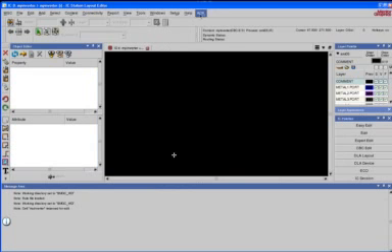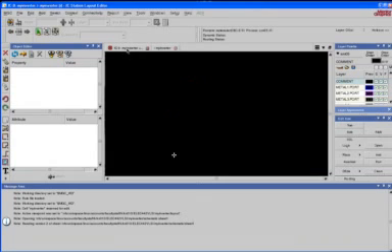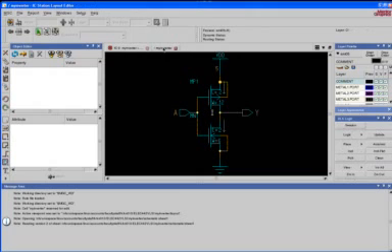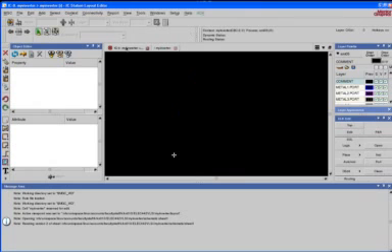Now this would bring up a window for my inverter. Click on ADK, so ADK palette. Click on logic open. Sometimes this logic window opens together with the layout window. So up here I have two tabs. This tab is for where I'm going to do my layout. This tab is for my schematic that I created earlier. Okay. All right. Go up here to my layout window.